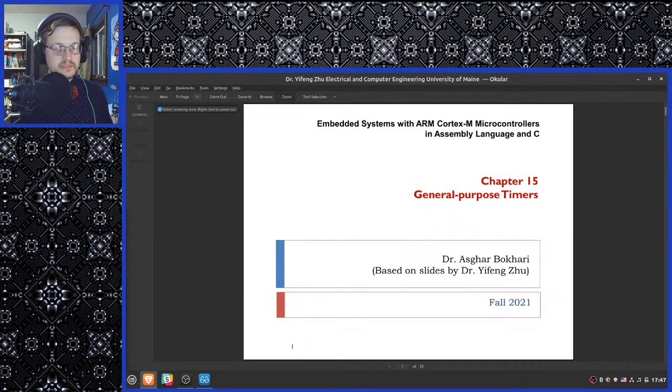The other thing about timing things with your software is, so you've got this timing code that's set up and running. What if it gets interrupted? Does not your timer also get interrupted? The answer is yes. Because an external timer is independent of anything that's going on in the software. And as we're going to see, external timers can be configured so that they cause interrupts in your software.